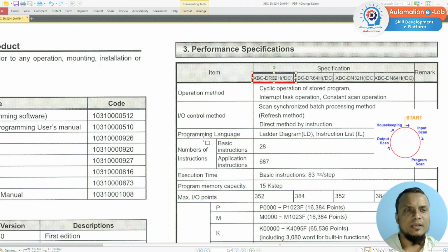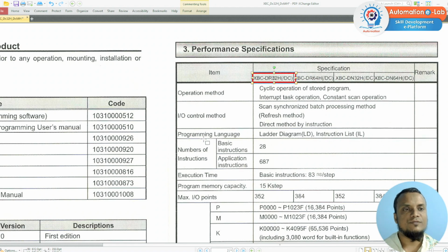Mainly, the PLC supports defined programming languages. According to IEC, all PLC brands should follow the ladder diagram, the common programming language. There is also instruction list and function block programming languages, but this LS PLC supports only two languages, ladder diagram and instruction list. Other PLCs like Siemens support function block diagram, instruction list, sequential flow chart, etc.